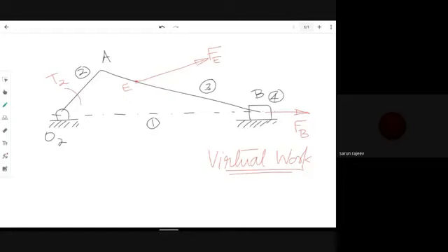During the discussion, the difference of that question was there was no link in the system which is a two force member. Each link number 2, 3, and 4 was having three forces. Link number 2 was a two force and a torque member. Link number 3 and 4 were three force members.